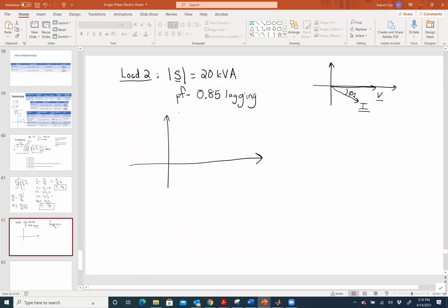So we determined here that this was an inductive load. That's what this lagging term meant. Okay. What's true about having an inductive type of load about its impedance angle? It's between 0 and 90. 0 and 90 is quadrant 1. So somehow I know that S is over here. Here's my magnitude of S. Okay. Here's Q. Here's P. And here's phi Z. I need to know that because my other load's going to be the opposite. I'm going to need to know whether it's capacitive or inductive.